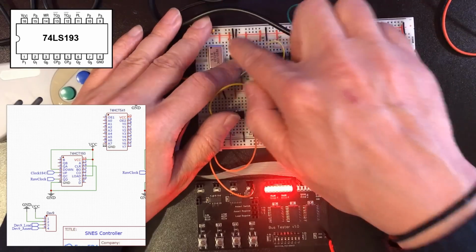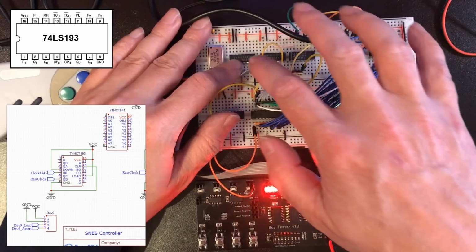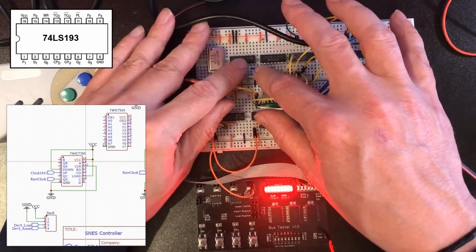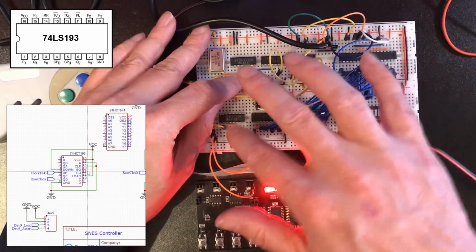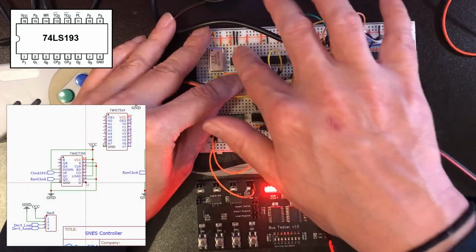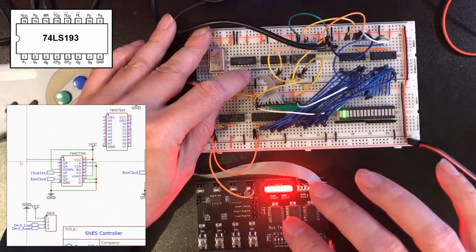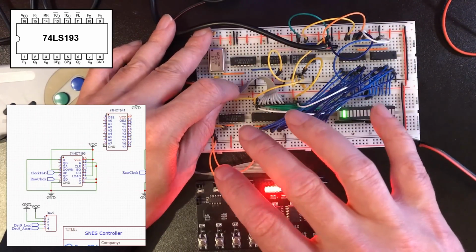Now, we've got 4 data inputs we really should be setting to something. We're just using kind of simplified breadboard circuitry to leave them floating. On the PCB, we'd have to pull all of the unused inputs either down or up. So I'm going to pull all of these inputs down so that then if we initiate a load, we get zeros.